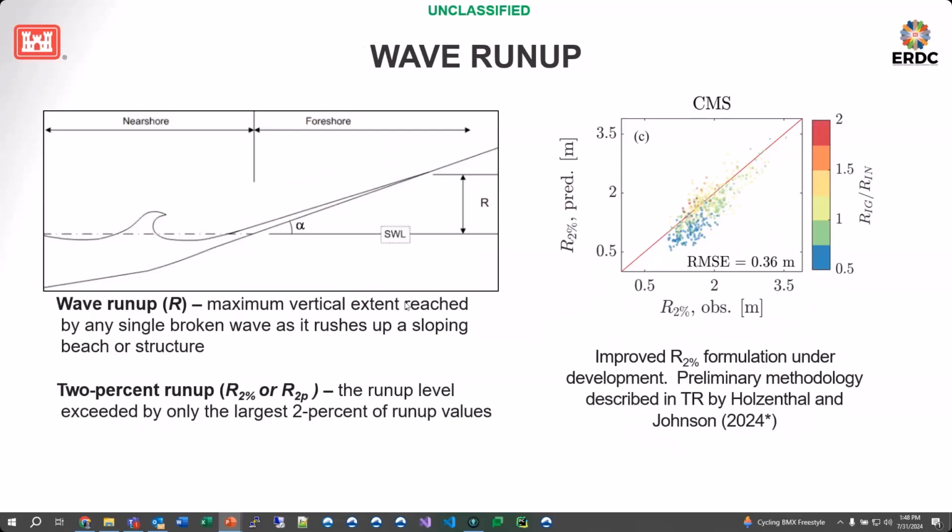Calculating wave run-up, we have formulations in place using the R2% to calculate what's going on. Before this, it was all based on what the actual bathymetry showed. So if bathymetry was above 0, that cell was turned off and you never got any kind of waves on top of it. If you turn on run-up, then the potential exists, if the wave energy is there and it shows that the wave would come on shore and wet that cell, then we do allow for some inundation of some previously dry cells due to wave run-up.